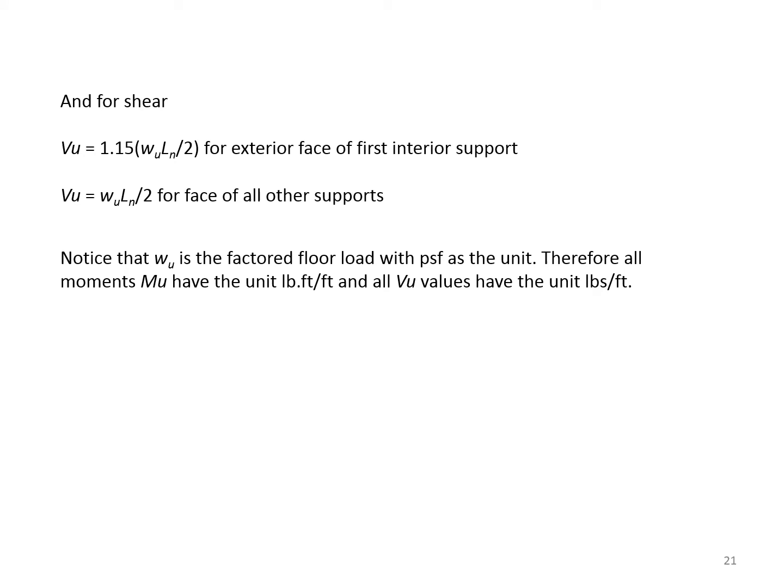Notice that Wu is a factored floor load with psf as the unit. Therefore, all moments Mu have the unit of pounds-foot per foot, and all Vu values have the unit of pounds per foot.